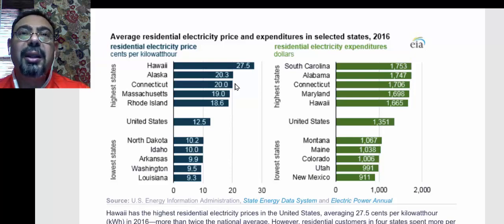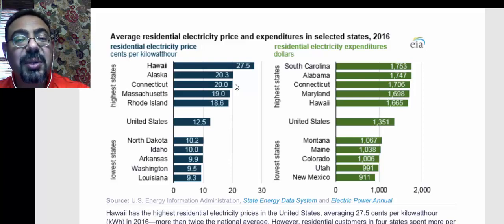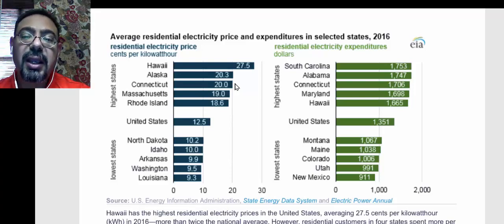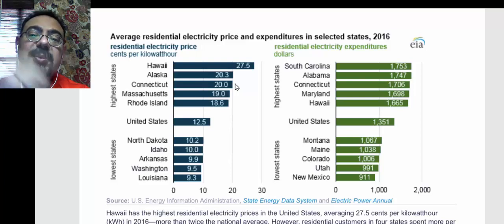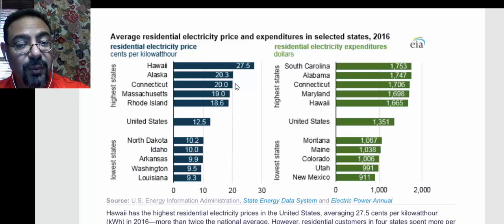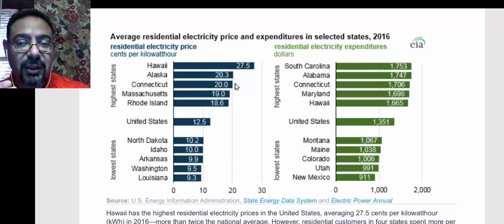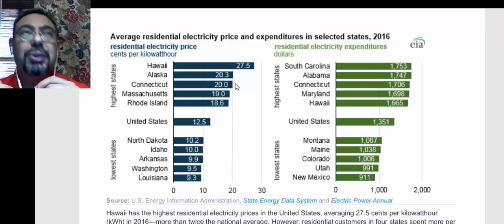That electricity, it's almost criminal to use it for heating, because we could just get heating by burning natural gas ourselves rather than using electricity to turn it into heat, right? Because that electricity again comes with 50% efficiency, right? So every joule that you would use in your electric stove, there is another joule of natural gas fired in the steam power plant that's being wasted to the sky, right? So if you used natural gas directly in your stove, you would use 1 joule rather than 2 joules of electricity.